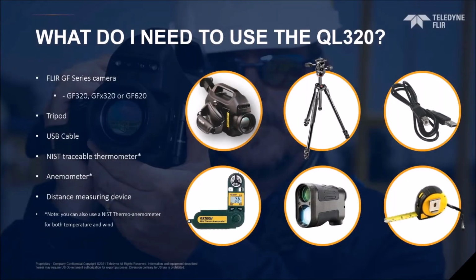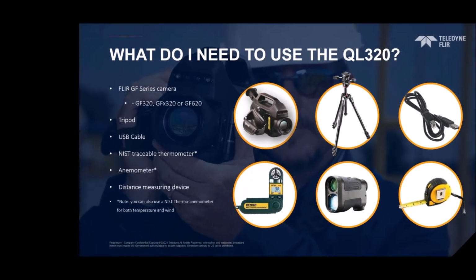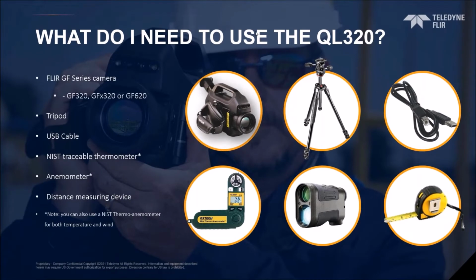When you're using this, there are really a few things that you need to have. First off, you've got to have an OGI camera from FLIR. This camera does have to be tripod mounted. The solution is watching pixels change across a screen, and those pixels changing across the screen may not work as well if your system is not steady. So you do have to use the tripod, whether you're using this in tethered mode or Q mode.